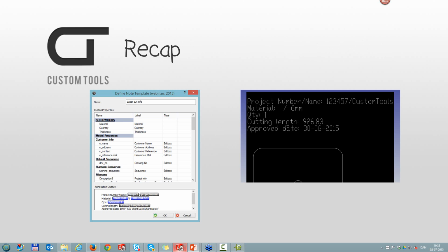So a small recap again. By using custom nodes, we can insert project information to our converted files also. This makes it really easy for laser cutting to place the cut parts in correct locations. It even allows them to copy the node onto the surface in the laser cutting software to engrave the number if required.